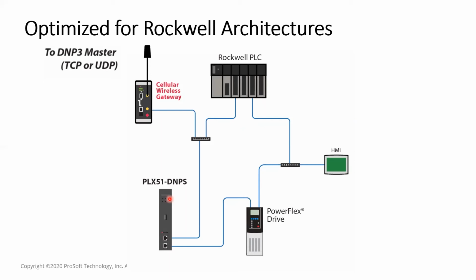Just to reiterate, there's no scripting, it's all configuration. Obviously, it works in tandem with the controller, the PLC, which is where you've got all of your logic, but the DNP3 gateway routes the messages. It converts the incoming through to DNP3 and then handles the communications through the top end.